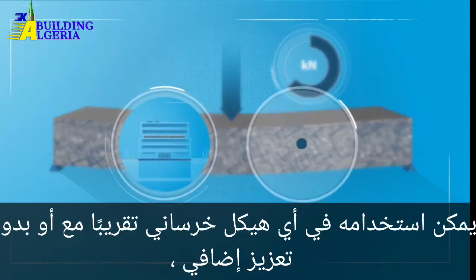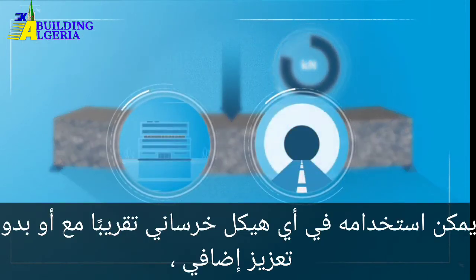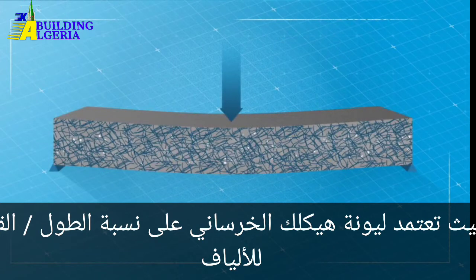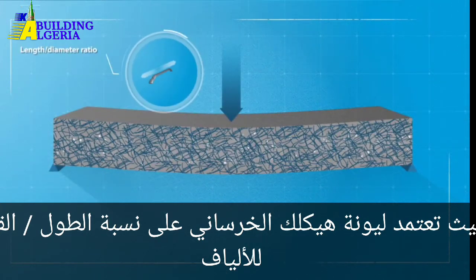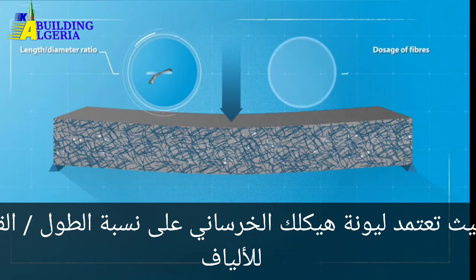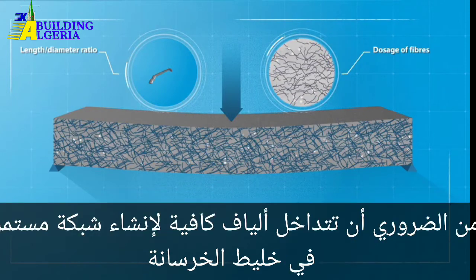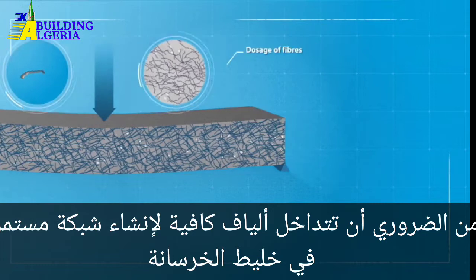It can be used in almost any concrete structure with or without additional reinforcement, where the ductility of your concrete structure depends on the length-diameter ratio of the fibers and the number of fibers used per cubic meter. It is essential that enough fibers overlap to create a continuous network in the concrete mix.